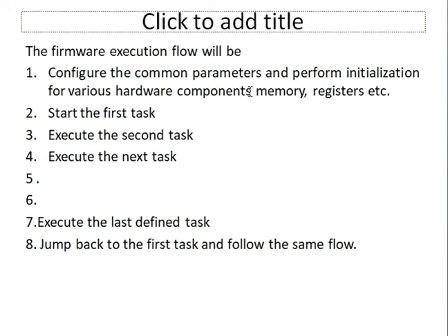What you are supposed to do first is configure the pins. Suppose you are using a controller, and some of the ports of the controller should be connected to an input device, and some ports may be connected to an output device. So the first job is to set the directional flag, whether the pins are configured as output or as input. Consider the example of the calculator itself.